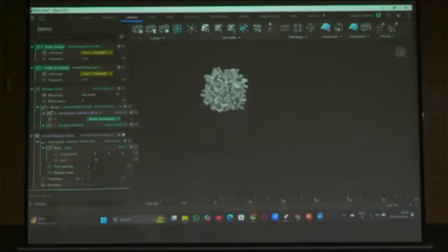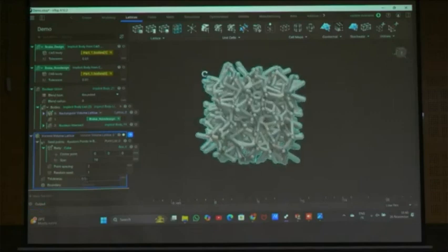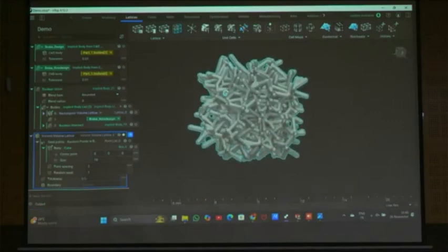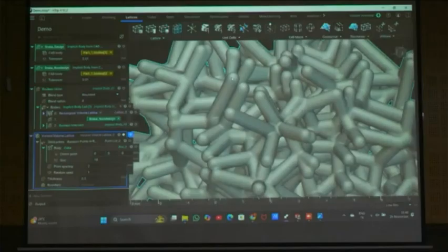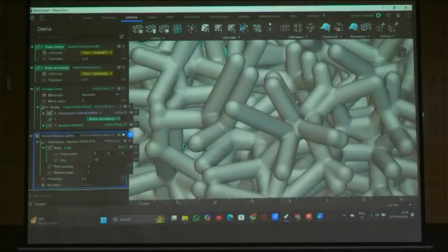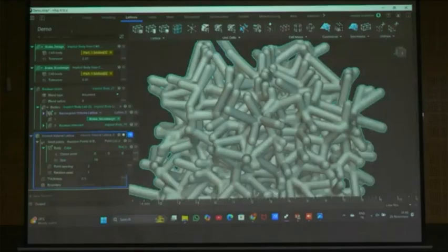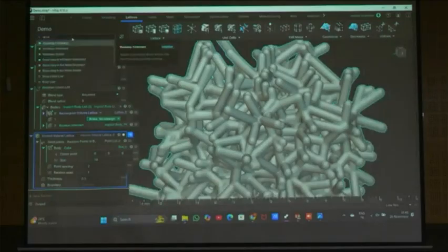like this. See, there is no uniformity in this actually. And one more thing, it is going beyond. See here you can see this one, right? The tapered portion is there, right? But we should not get it like this. You can see here the tapered portion, we need to get it exactly, so we can go with the Boolean intersect here. I will show you.